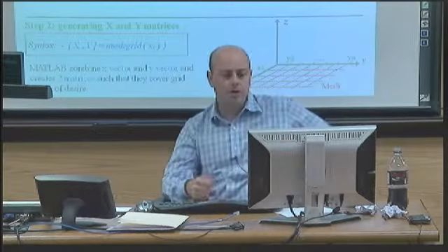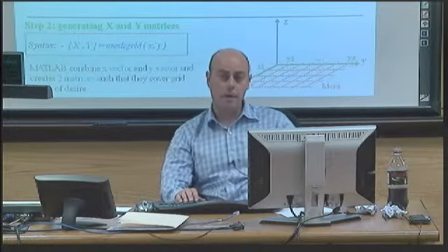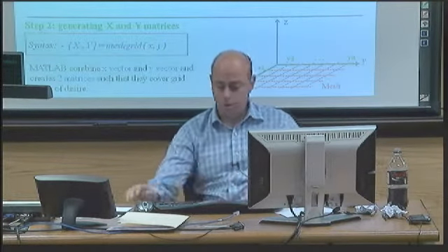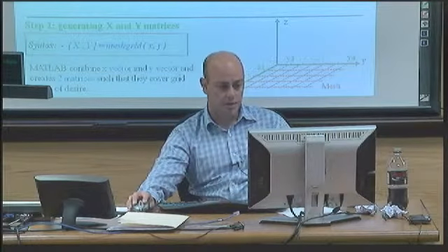So all I give you is a function, z is equal to... we're going to use something called meshgrid, which isn't a plotting tool at all. Meshgrid is just a way to create a grid on a Cartesian grid, kind of like the picture I've shown right there. Let's say I've got an x and a y vector.